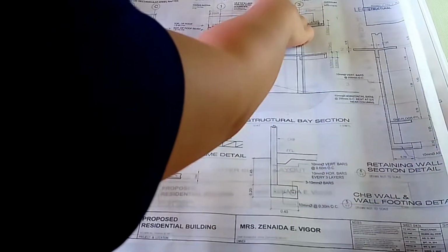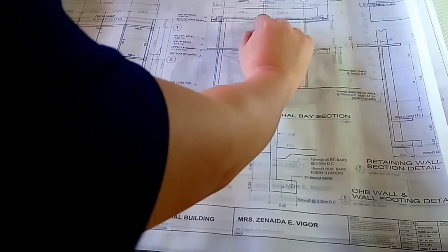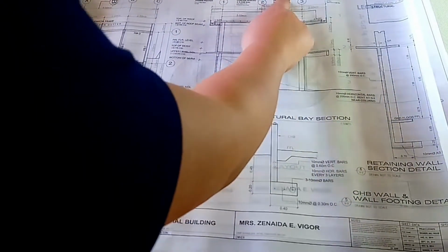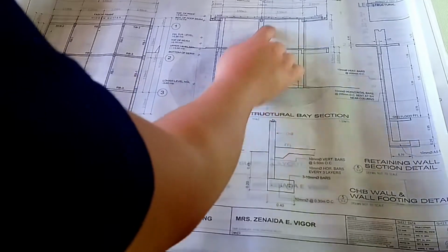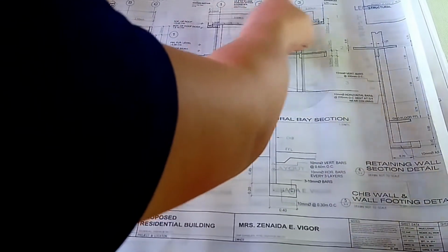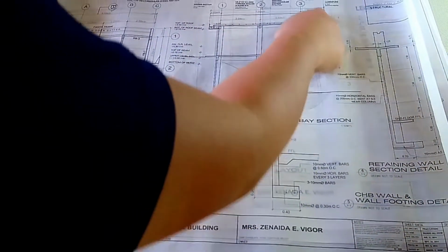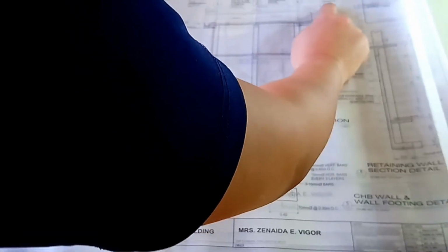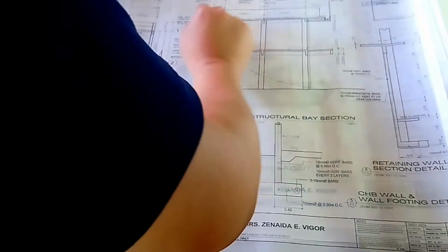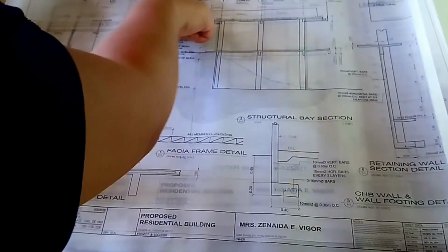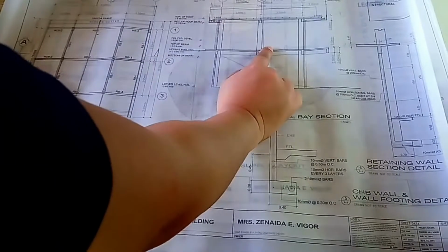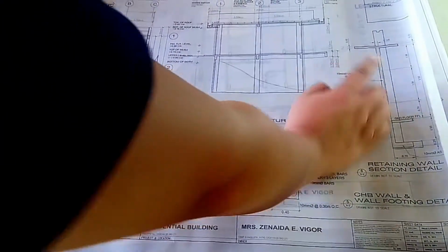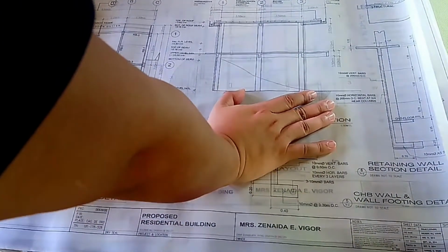Then we also have seam block roofing from Union Galvanized in the specifications. For the rafters, we're going to use hollow rectangular rafters. This portion here is the firewall. Then we have here a fascia or stiffener, and some hardiflex attached to the underbar. Also here you can see the detail for the basket drain and the hidden gutter. Okay, so this is an example, class, of a base section, so it's not that hard.